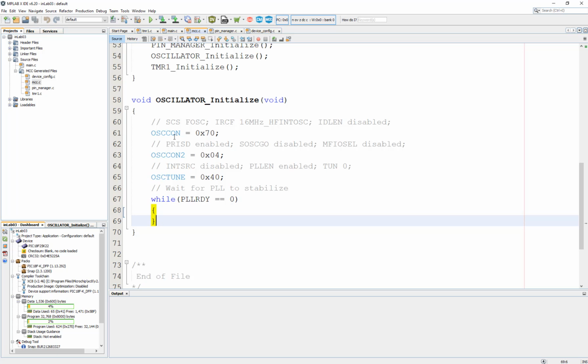After you go through the MCC, if you go to the website, go to the data sheet, you can find out the registers. For example, I'm searching for, you see OSCCON, right? By looking at this short name, you know it's oscillator control. All the time you see CON, C-O-N, it's a control. So controlling the oscillator frequency, I could tell.